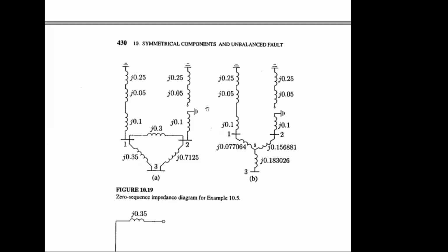Okay, sir, I understand, sir. Okay, okay. Sir. Y delta position will give you indication whether it should open or not. So based on that, and it is applicable for only zero sequence circuit, not for positive, not for negative, only for zero sequence circuit. Okay, you have to be careful about that. If it has any delta, you have to draw the circuit accordingly based on the zero sequence transformer equivalent circuit.